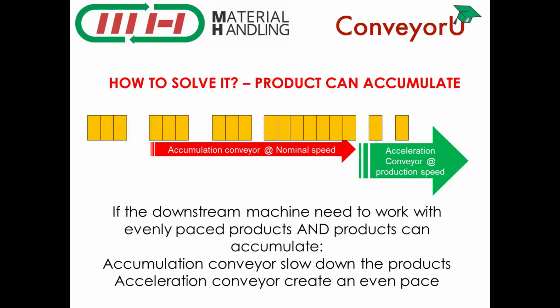So when the train of product arrives at double the speed, they will slow down, possibly sliding on the accumulating conveyor, and when the other train arrives, it will immediately close the gap that it has with the train before, because the accumulating conveyor is running at exactly the nominal speed. Okay, so on this accumulating conveyor we'll have all the products touching one against the other, and to regularize the pace, all that we need to do in this case is very simple.